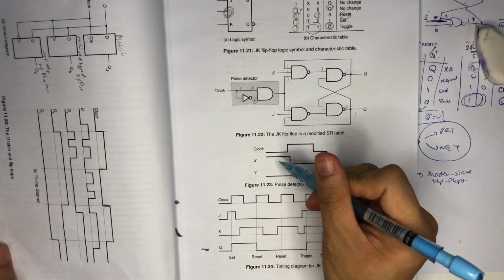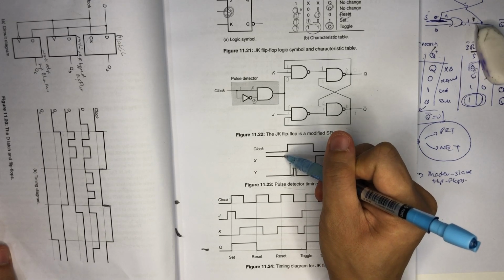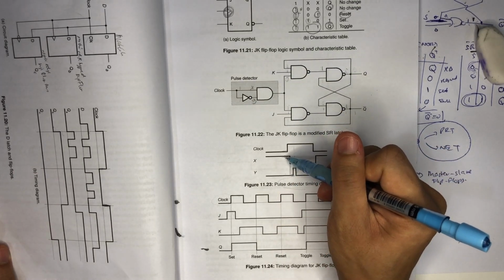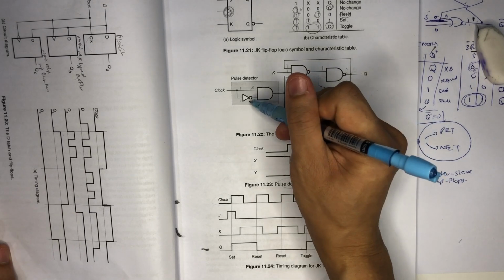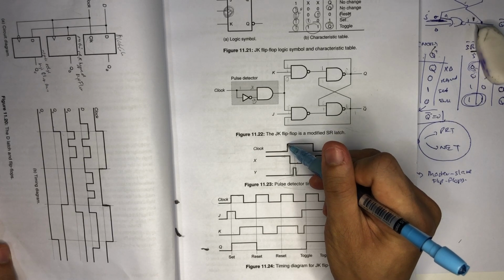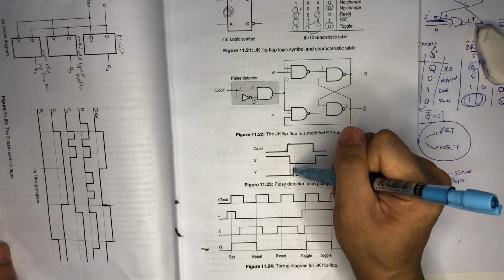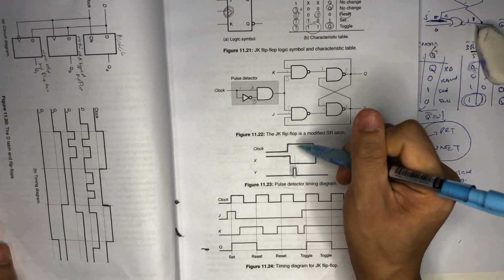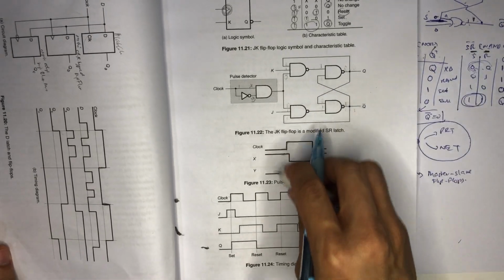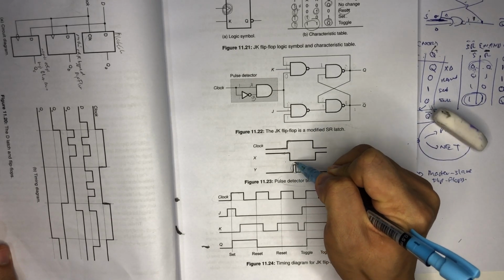Let's say while the clock is like this, this is 1 and this is 0, because you can see it's always opposite, because you have a NOT function. Then when the clock rises, this will rise and this one will be 0, and you can see there's a small delay. When this is 1 and this is 0, they will be slowly turning up. You can see it's not direct here, it's slow. So this is the short pulse.